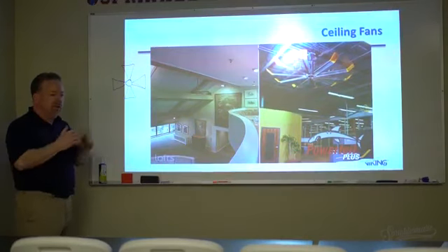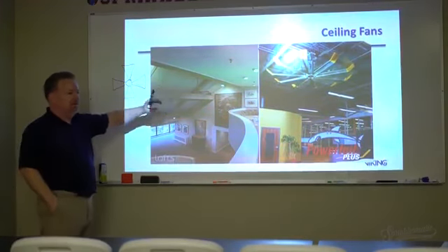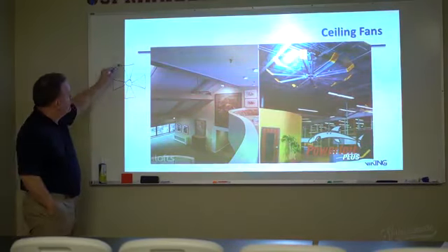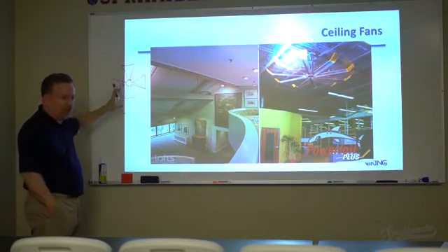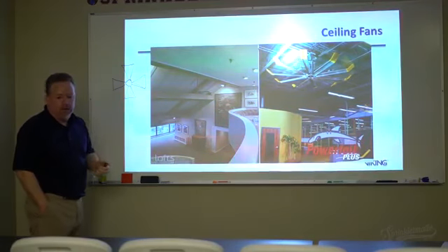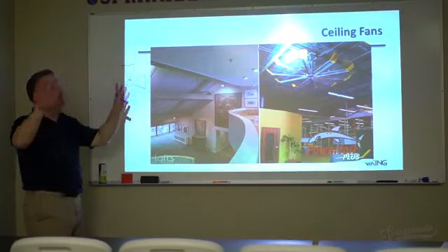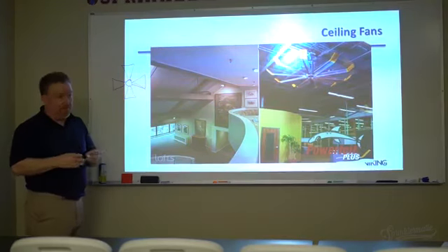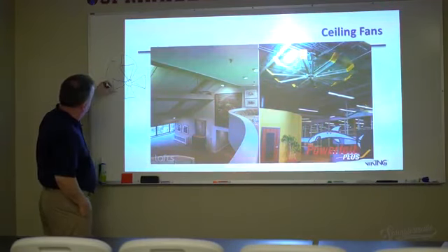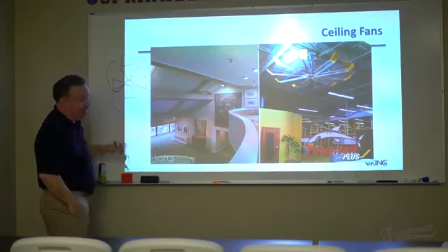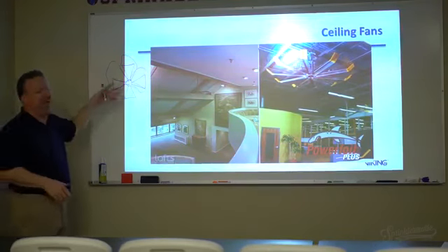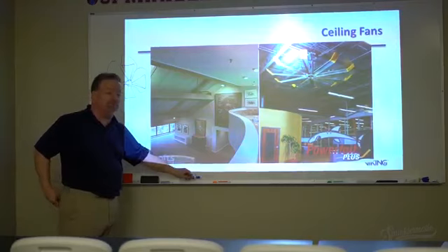But what happens when we put these in a restaurant, and it's Joe's restaurant, just regular standard old bar fare, and we've got the ceiling fans and they're all set fine, they're all great. Then Joe's goes out of business, and in comes the tiki bar. The tiki bar wants a whole new motif. And so what do they do with the ceiling fans? Ever seen these? Put the palm fronds on that overlap each other like that. What have they just done? They've just created an obstruction to my spray pattern that didn't exist there before.